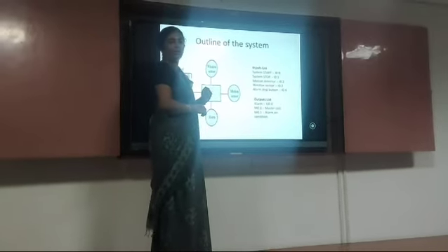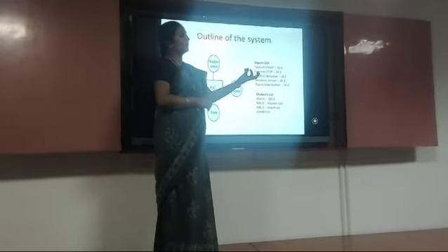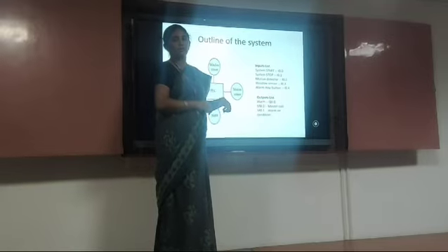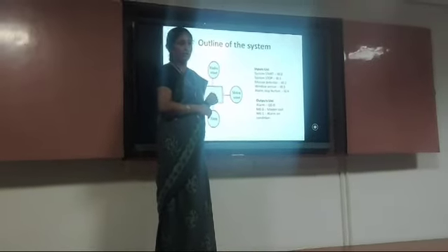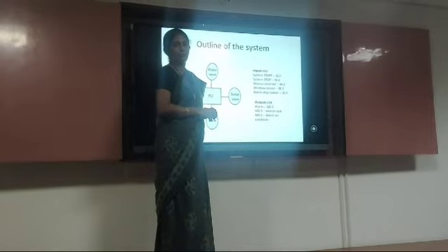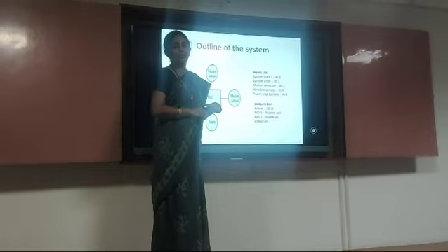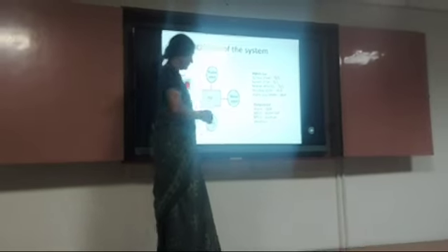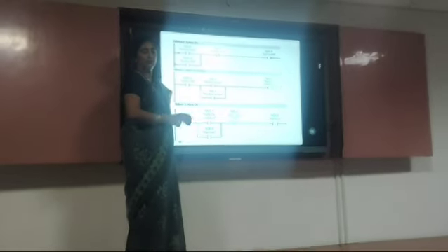And if any of these conditions happens, that is, if a person is detected inside the house, or if a person enters the house through the window, if either of these conditions happens, an alarm should ring. So we are going to design a PLC for that. This burglar alarm system should be activated when we leave the house. So this is the PLC ladder logic system developed for this.